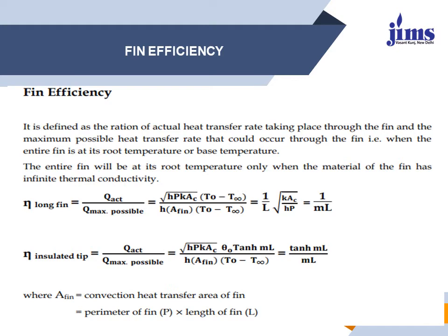So if we talk about the fin efficiency, the efficiency of a fin is defined as the ratio of the actual heat transferred by the fin to the maximum heat transferred by the fin if the entire fin area were at the base temperature, or it is defined as the ratio of the actual heat transfer rate taking place through the fin to the maximum possible heat transfer rate that could occur through the fin when the entire fin is at root temperature or base temperature.